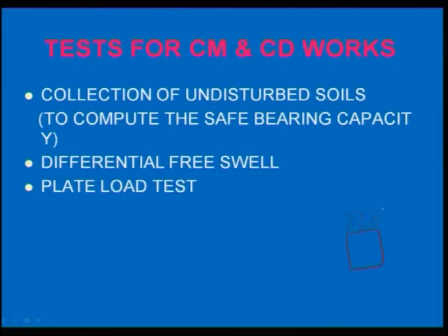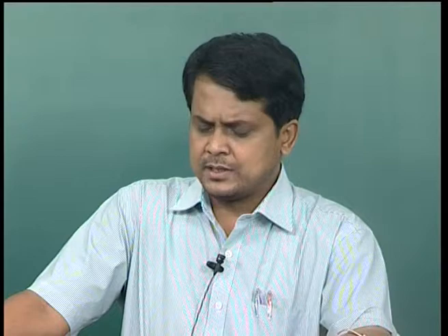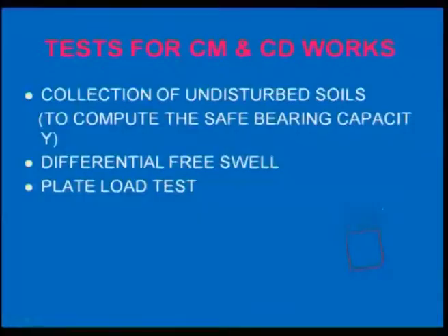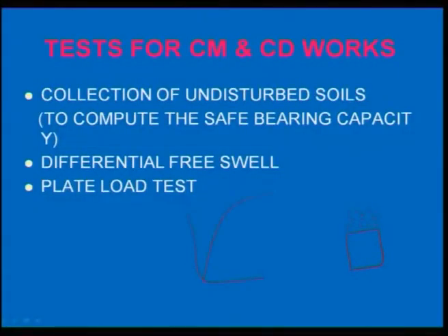Generally in the lab we do this swell test by taking the soil sample and putting it in the oedometer equipment, then applying certain loading, then applying water, and allowing the soil to swell for a day, 2 days, 3 days, 4 days, even months together. We record how much swell pressure or swelling we get over a period of time. Swelling goes on, and somewhere it remains constant. That means no further swelling, and at that point we stop the test.